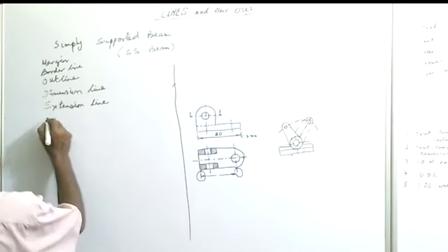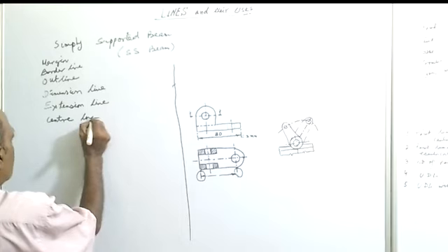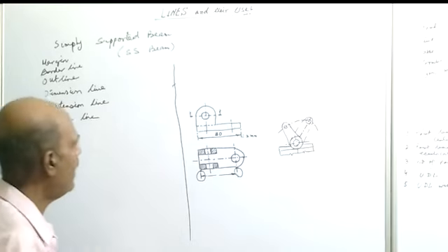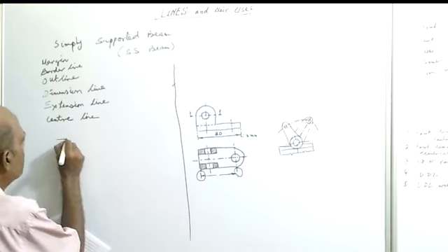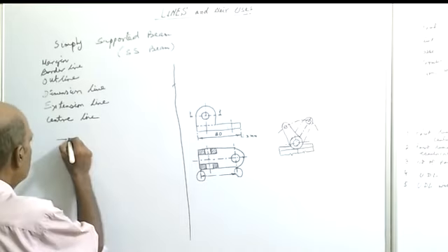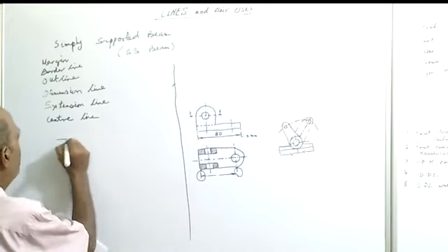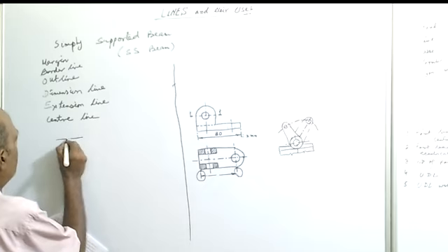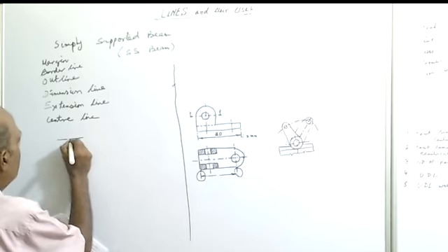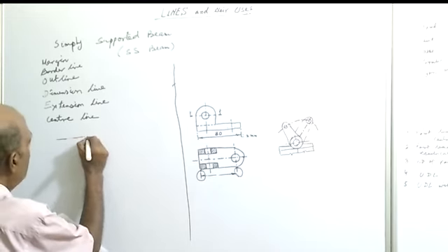Next we will see the other kind of line, that is the central line. These lines are thin lines and drawn like this: 3 to 4 mm, then put a dot here, then leave 1 to 2 millimeter, and so on.